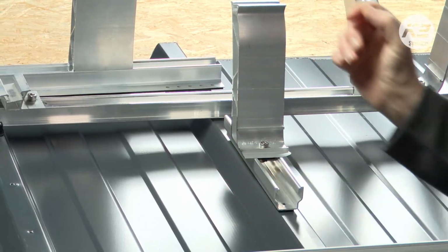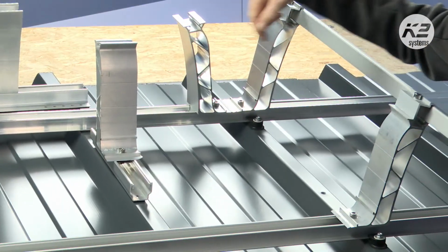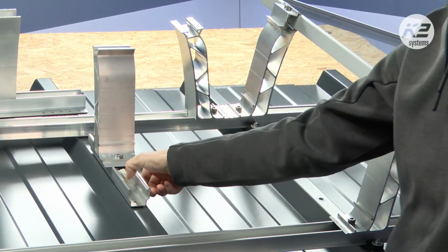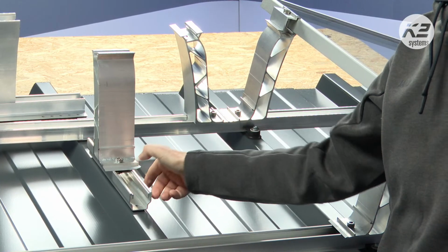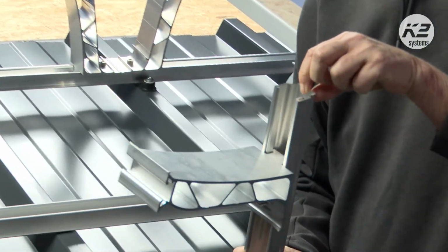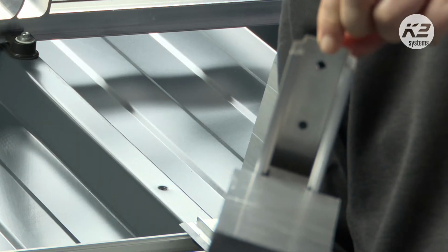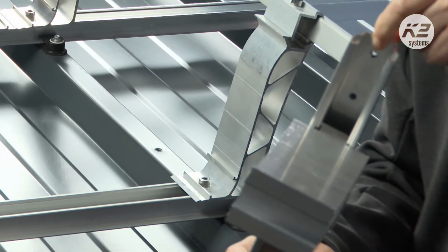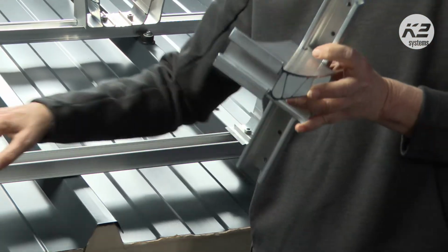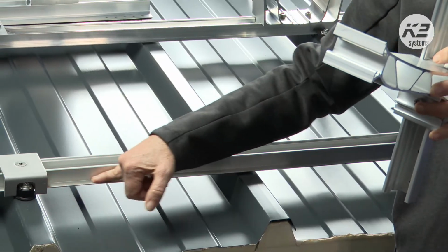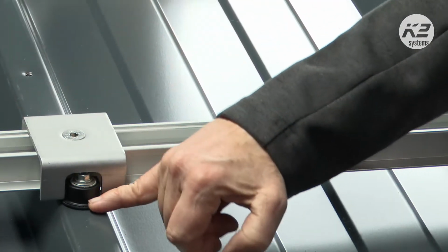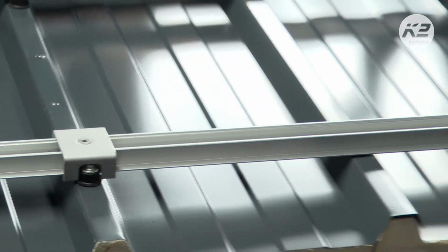It's okay. You see the same component like here, a peak, but the rail is different. So this is a BasicRail, and this is called MultiRail. It's different because for that MultiRail, you see there are some holes in there, and the method is that we screw directly through those holes in the sheet, in difference to the BasicRail, where we have as an additional component this basic lip. We don't need that for the MultiRail system.